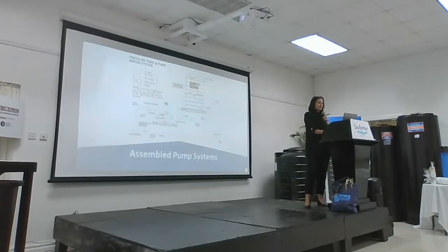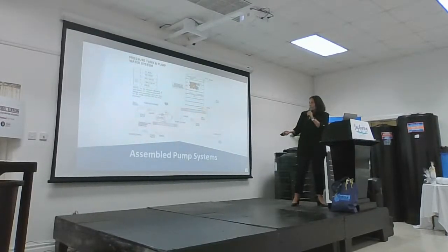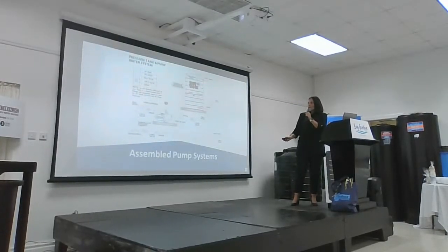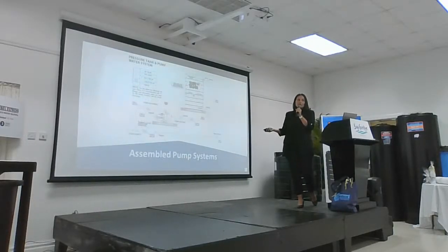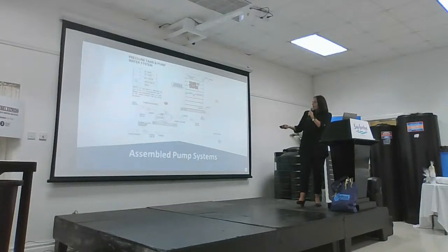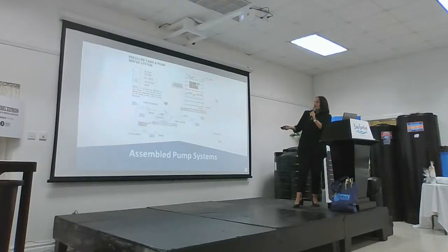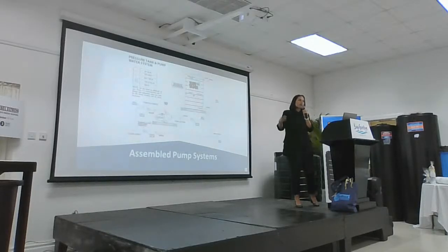Of course, with pressure tank systems, installation is very important. So we have our Zilmet Pentax water pump system here. You always want to make sure that you have on the suction a check valve to prevent backflow and to maintain the prime in your water pump, as well as a union for easy servicing. And then on the discharge, you will also have a union, another check valve as well to maintain the pressure, and a ball valve to turn the supply of water on and off.